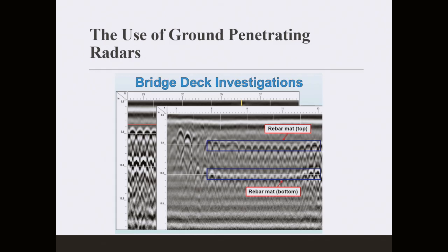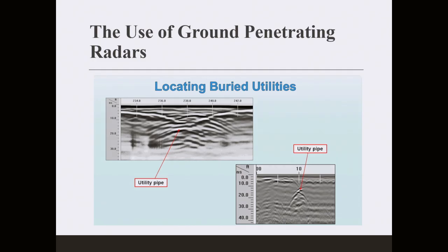So this is the GPR, and it's good that it can tell you what's going on under the surface. You can inspect inside a concrete section, under the pavement, within the base or the sub-base, or even the soil layers, or the existence of caves. So it is penetrating. Why am I saying this?